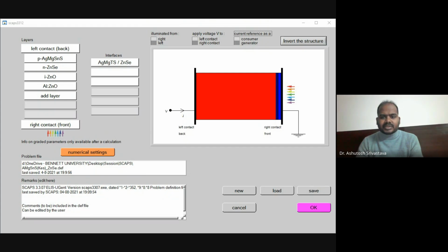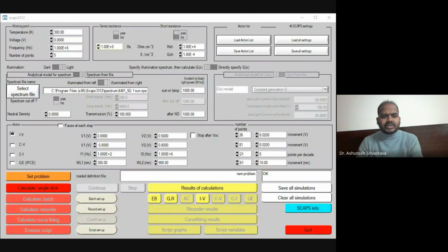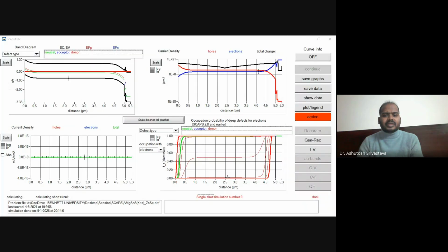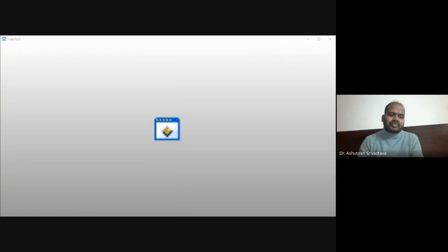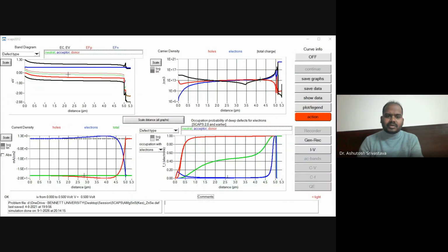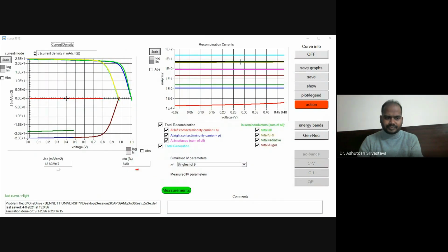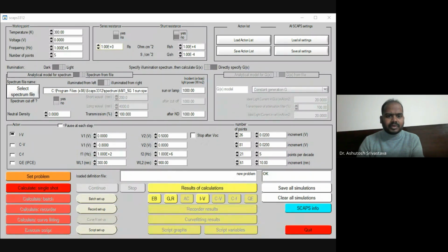So what is this convergence error? Let's see whether it gives you that error or not. The standard value that we got was 2 micron, but I changed it to 5 micron. Let's see how it all goes. Yeah, I got the values. Again, it's an error because it has not reached the point. If I improve it to 1.5, since I'm using a device which is actually the correct one, I'm not getting that convergence error.